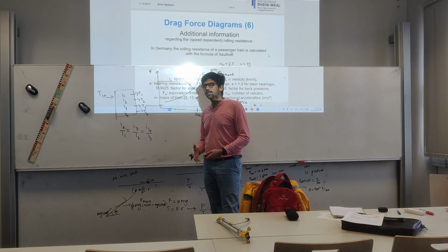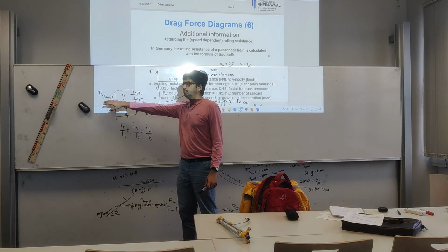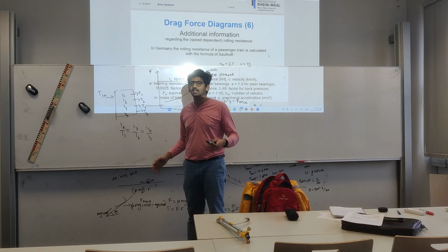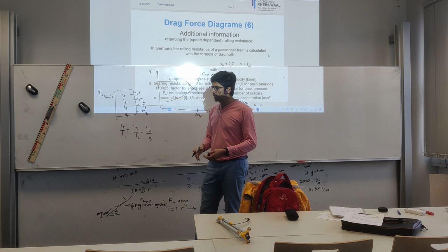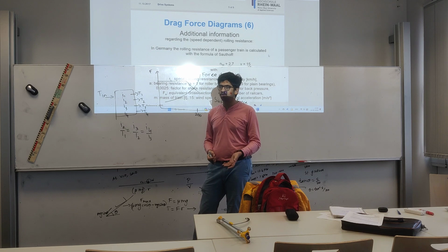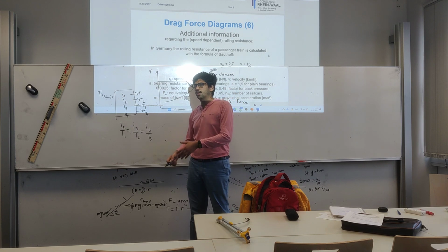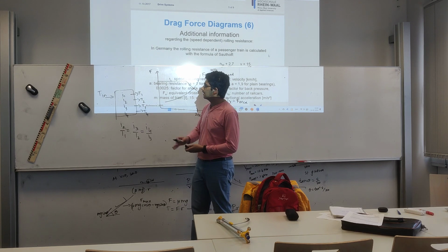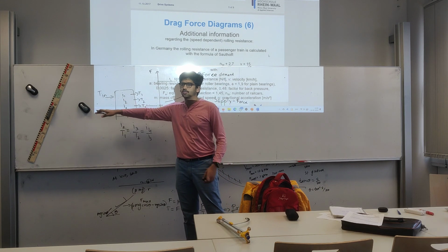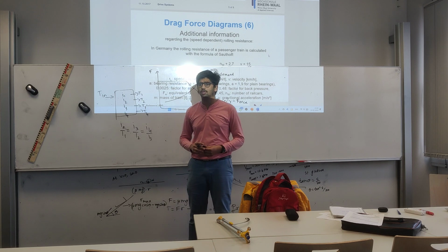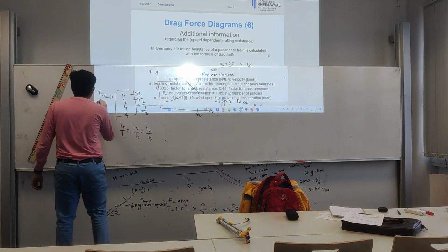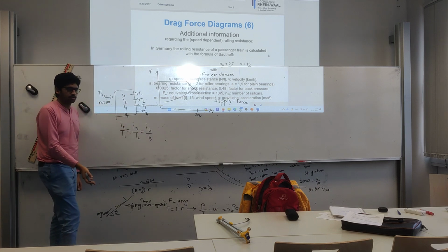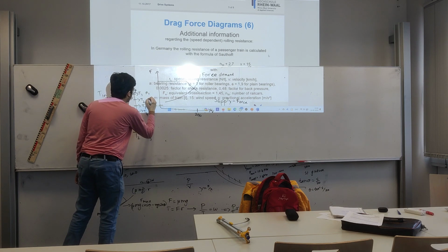And you use that to find out how many gears you need to split your range into, because when you're designing a gearbox, you know your input torque and you know how wide a range you need to go between. Let's say for a tractor, it needs to plow the fields at like 5 kilometers per hour, but also pull the trailer at 70 kilometers per hour. That is your speed range. They take the input RPM to be constant because the diesel engine runs at around 1400 RPM, and the wheel size is constant. So the RPMs are changing.